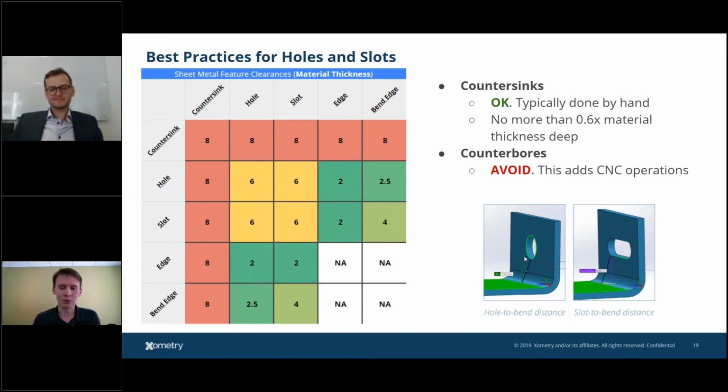But that's something that's extremely common. And I know we're about to talk about relief cuts and other things. There are some ways to mitigate this, but it's an extremely common thing that we see, features too close to the edge. It's not always holes. Say for example, I'm making a router box and I have a port for a VGA cable going through. It's very common for me to see those ports designed right next to a bend, and it creates almost a fat lip. It'll curl out on that, and because that stress is going somewhere, it's going right into your feature set.